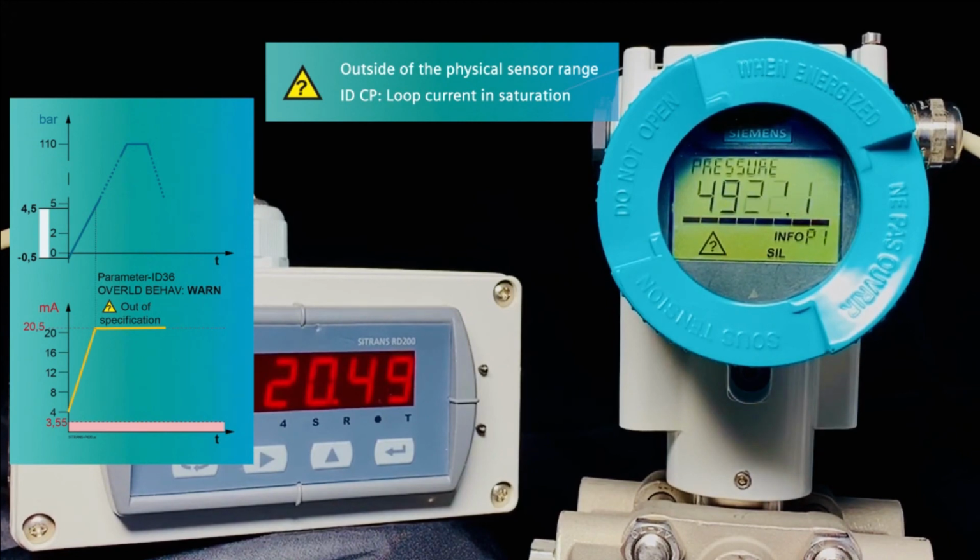If I increase the pressure further, the diagnostic message changes to CU. This means PV status uncertain. The value is outside of the physical sensor range. However, the output current remains in saturation.